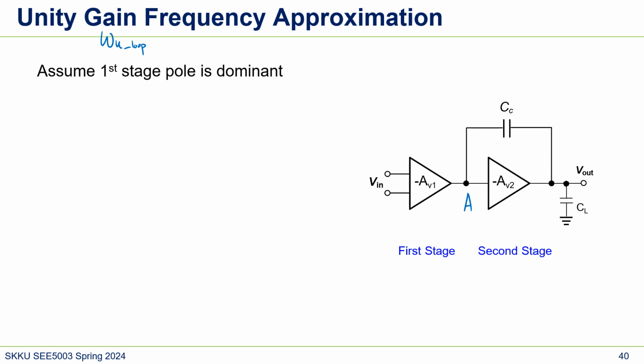So this one is node A, and then we're going to assume the first stage is that 5T transistor amplifier. So the first stage gain is GM1, RO4, RO2. Now you can just refer to the previous slide about the schematic. That's the gain, and then if we just draw a Bode plot,